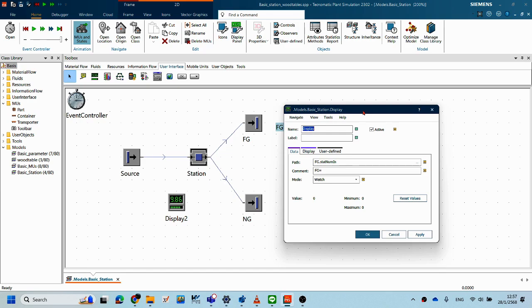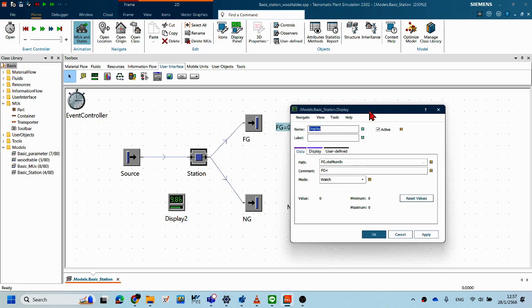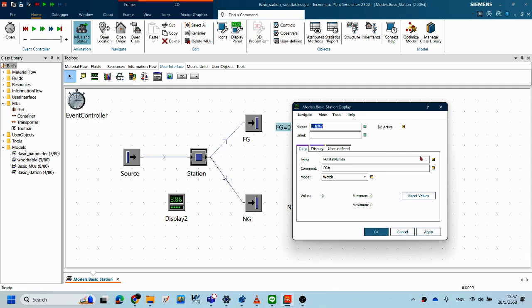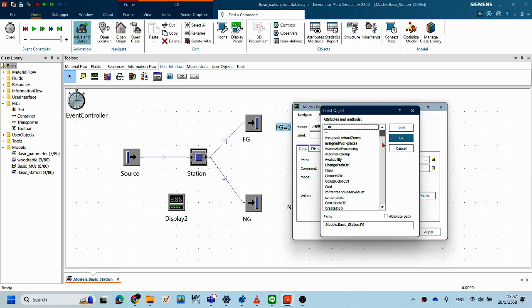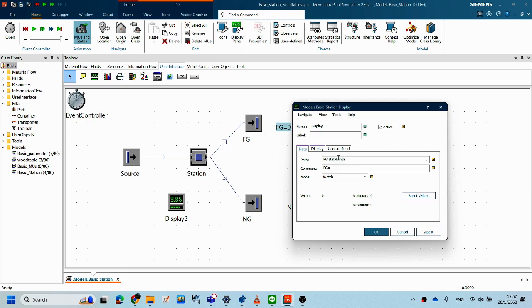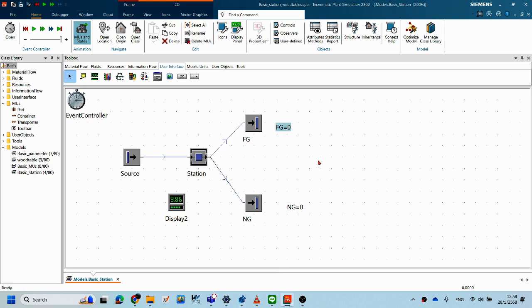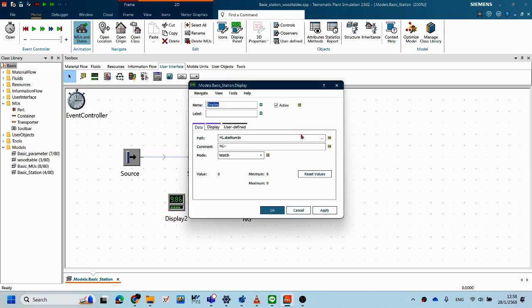How to show some parameter when you need it: if you need a parameter to show up on this display, you can find it by using the three dots after this blank box. Click here, and you can find the value you need to display. Click on that parameter, this one, and you put in the comment. Last time I showed you how to set up on here already.